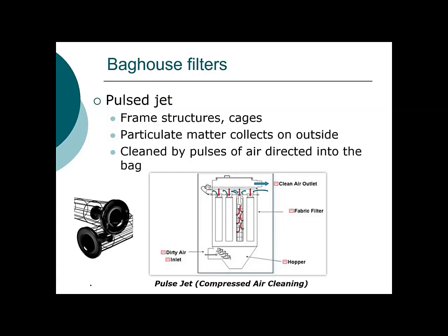Typically here, the particulate matter is collected on the outside, so it's what we refer to as an outside-in mode. And so the dirty air is collecting on the outside, and you're pulsing air to dislodge that material.